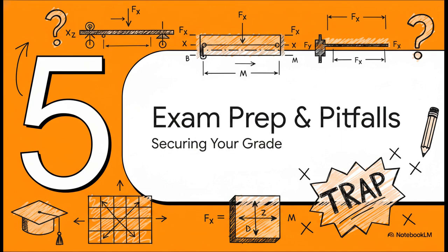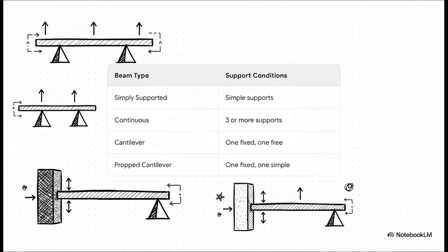Section 5. Exam Prep and Pitfalls. Let's secure that grade. That right there is the magic of the free body diagram method. But to ensure you execute it flawlessly, use this summary table to instantly recognize how different beam types dictate exactly which support restraints you've got to calculate. A simply supported beam just has basic end supports. A continuous beam spans 3 or more. A cantilever? It's fiercely fixed at one end and totally free at the other, meaning you absolutely must account for that fixed restraint moment. And a propped cantilever mixes them up. Fixed at one end, simply supported at the other. Instantly recognizing the beam type tells you exactly what reaction should be on your diagram.